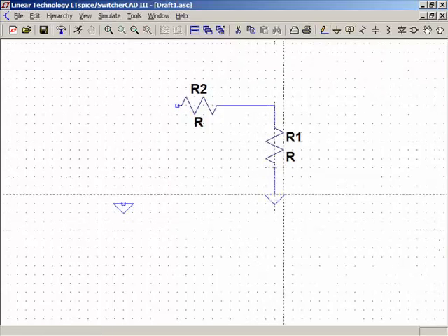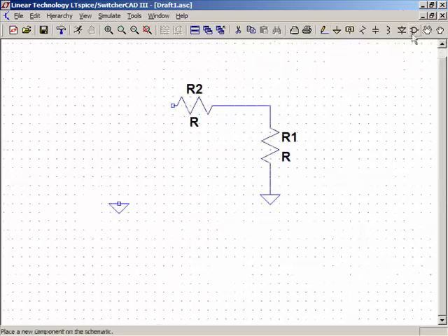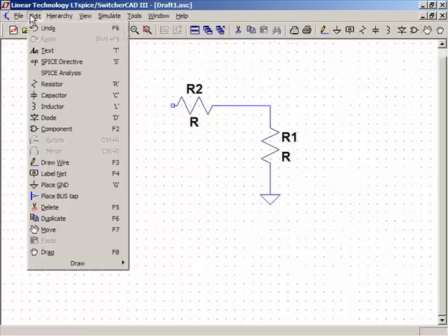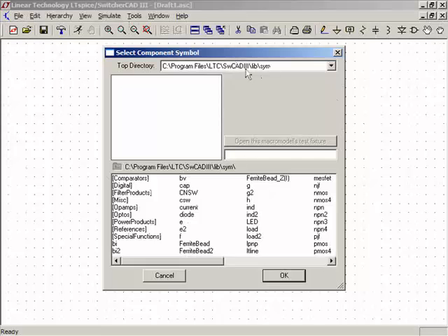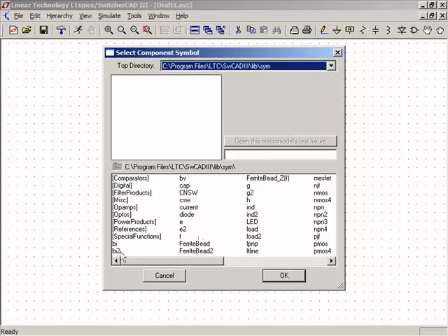I'm going to collect the wire there. Then I'm going to go to these components, and let me see. Can I put... oh, there's components just by pressing F2. So I'll go to components, and I'm in the basic library of symbols. The first thing I'm going to put, I've got all these things that come from Linear that I can use, but I want to keep my sim simple because I'm new to Spice.